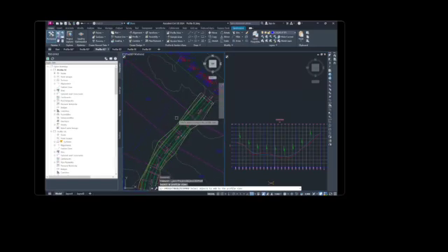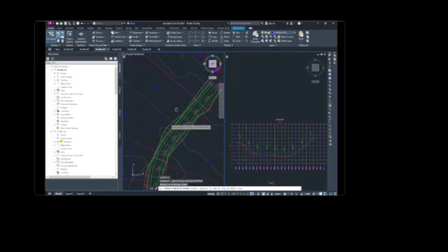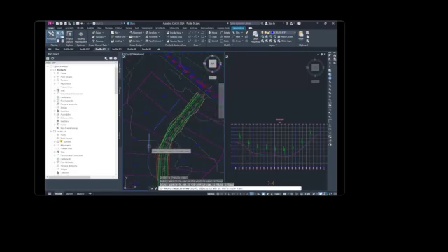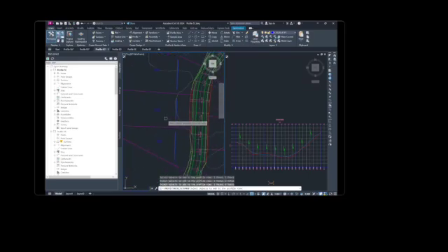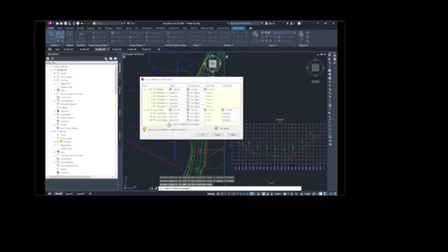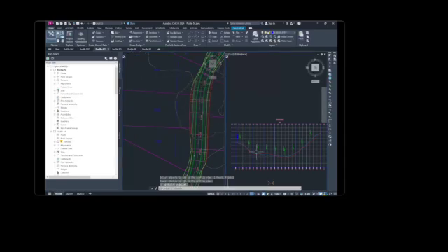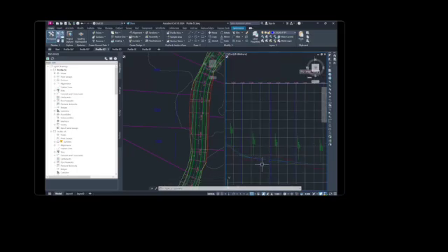In the left viewport, zoom out and select each of the blue 3D polylines that represent the front of building footprints. 1, 2, 3, 4, 5. Press enter. In the Project Objects to Profile View dialog box, in the 3D polylines row, under Style, click Set All. In the Style box which appears now, we're going to select projection without exaggeration. Good. Click OK, and click OK again. The COGO points and building 3D polylines are displayed in the profile view.